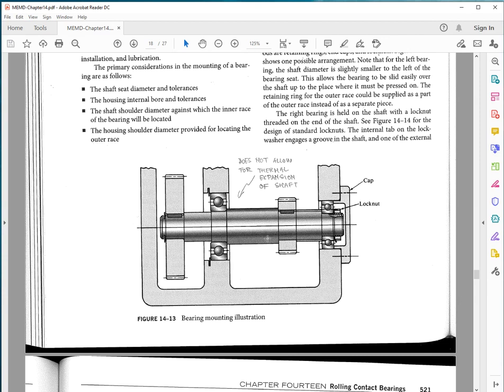And also, if they are straight spur gears, thrust is negligible, but if they are helical gears, you would definitely consider the bigger bearing, the one that takes the thrust load. Okay, sometimes with helical gears you can get the helix angle negative and positive here, and they could partially, if not fully, cancel each other's effect. Okay, but these appear to be gears, if not sprockets, for timing belts.